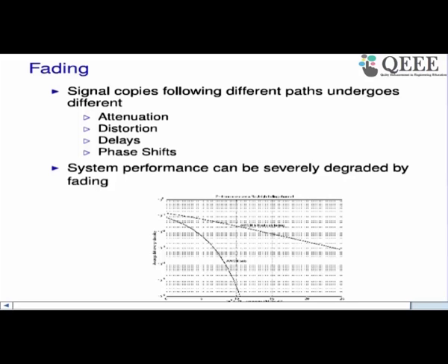So you see that if you extrapolate this curve, the curve that is going linearly down, this would go to around 10 power minus 6 at around 50 dB. So what you require is 40 dB more power to get a performance that is acceptable on a wired line. That is a huge amount of power, 40 dB.